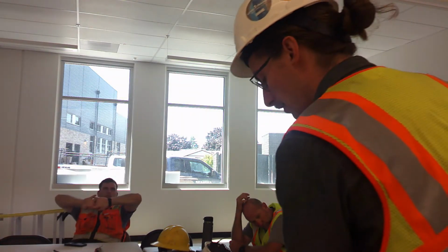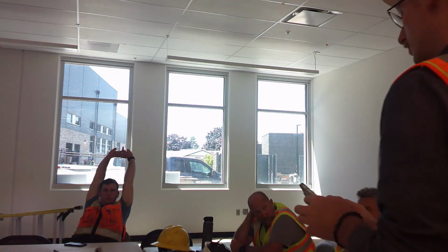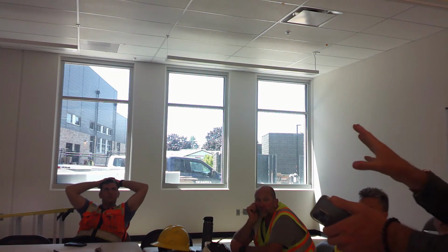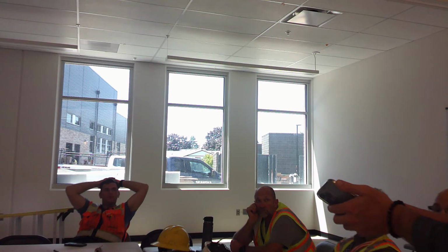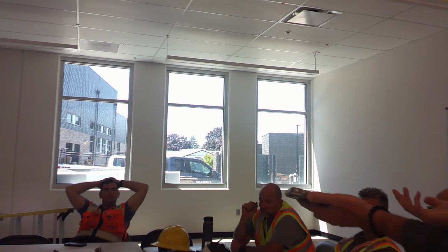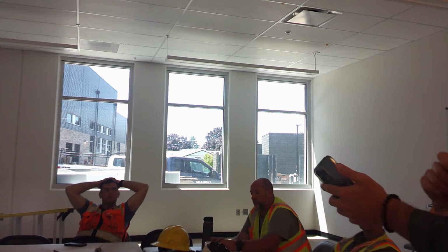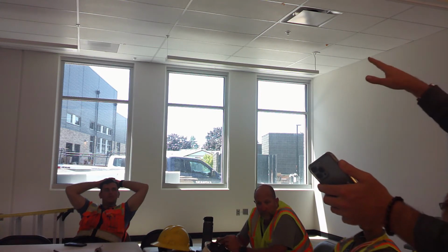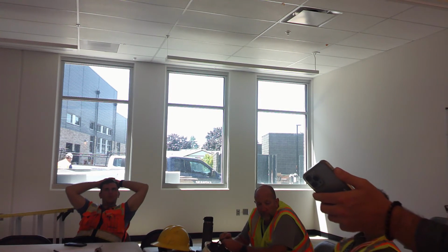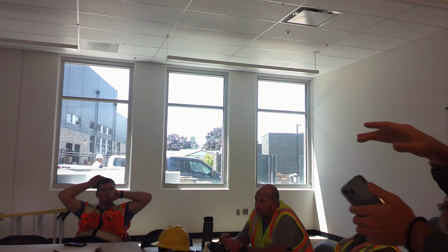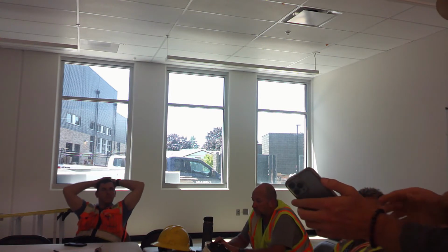So you'll find, didn't talk about the photocells yet. You'll find the occupancy sensors are just going to be in all the groups. That's by default. And so they'll just control everything in the room, which is what you want. The daylight sensors, however, so per daylight sensor input, you'll have 6 zones that you can individually tell it how to control and calibrate.